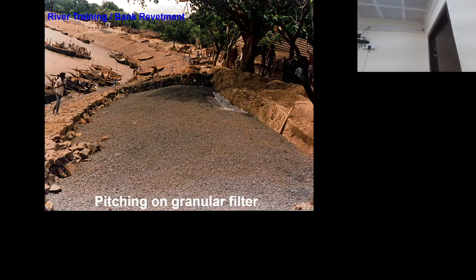Nowadays we are using geosynthetic filters; earlier days they were using granular filters. The geosynthetic filter will be provided along the total launching apron. This is a very important thing. Nowadays we are using geosynthetic filter, and earlier they were using granular filter like this type of granulars.